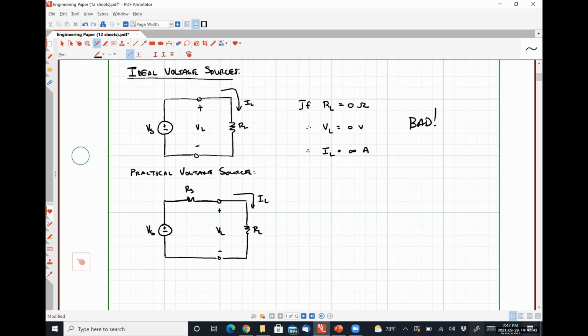So the internal resistance of, say, a standard 1.5 volt AA cell is on the order of 0.05 to 0.1 ohms. It's not a very large quantity whatsoever. What that resistance does is it limits the amount of current that could be possibly supplied by that battery, right?